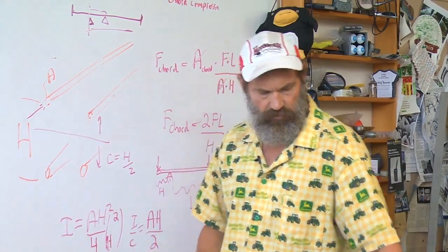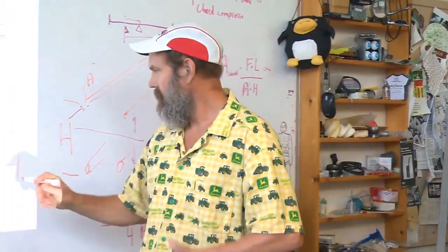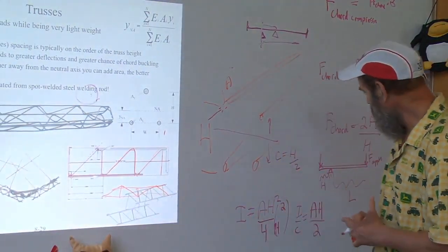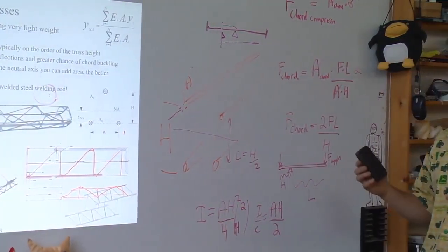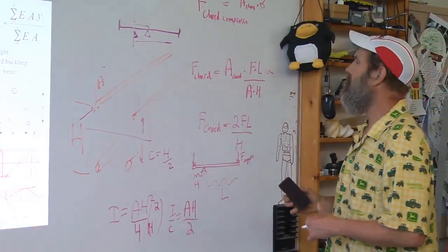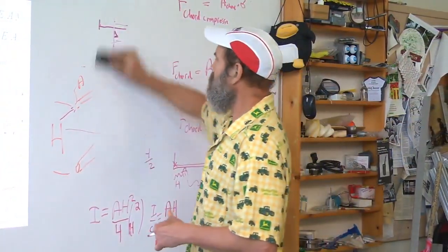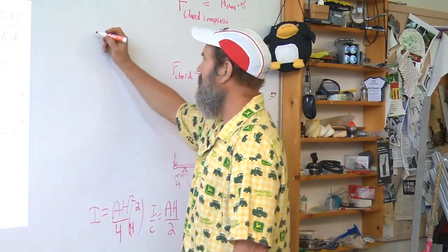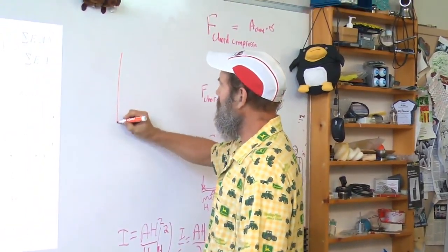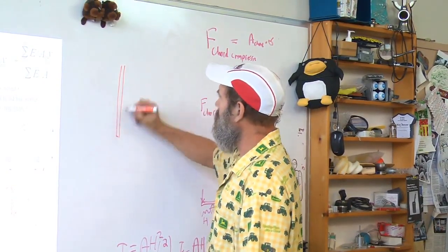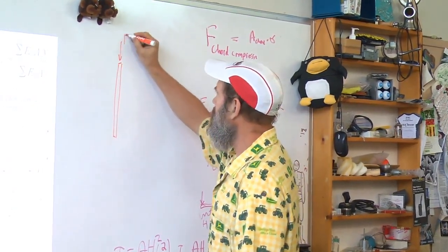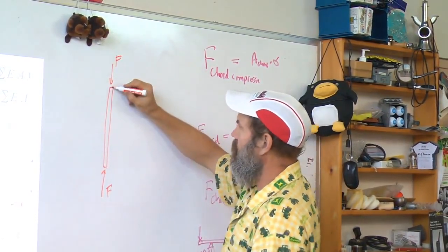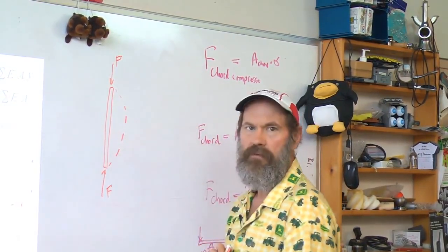How does that get to where these diagonal braces go? Well, now you get back into good old-fashioned column buckling. And remember this from topic 5 even. We talked about stability of columns or shafts, and that if I have a column and I push on it, how hard can I push before, bam, it buckles?